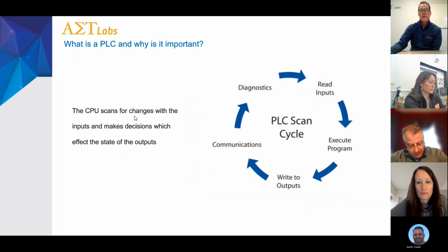So just like any computer, there's the CPU that does the processing power. It's going to scan. It's going to read the inputs. It's going to execute a program. It's going to write it to the outputs. And then you've got communications that are within the PLC, or it could be communications externally. It could be like a network, like an Ethernet network that it communicates this to. There's also diagnostics within the PLC, so it might be scanning and looking for any kind of issues. But it's doing this constantly. It's doing this every couple microseconds, whatever it's scanning.